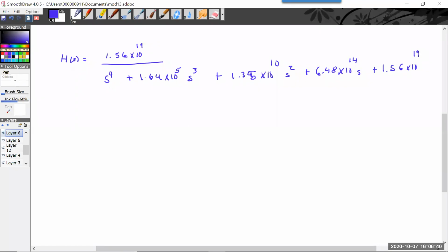Now, let's do a 4th order low pass filter. And this comes from the same program. You just tell it the cutoff frequency, which is supposed to be 10 kilohertz. You tell it 4th order, and then you tell it the Butterworth style, and these constants come out. And I look at this and I see it's just like before, right? I can modify everything.